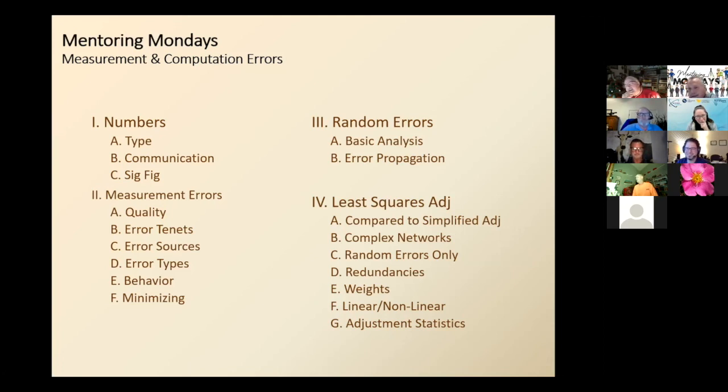Well, one of the other things that gets me about some of those pincushion situations is that when you're chasing around all that stuff, it's not statistically significant. If that's a PLS monument that was originally set at a certain accuracy, and you're looking at all the evidence you're trying to evaluate now, and it doesn't point to a unique location, there's going to be uncertainty in that position to begin with. So why bother popping another monument in?